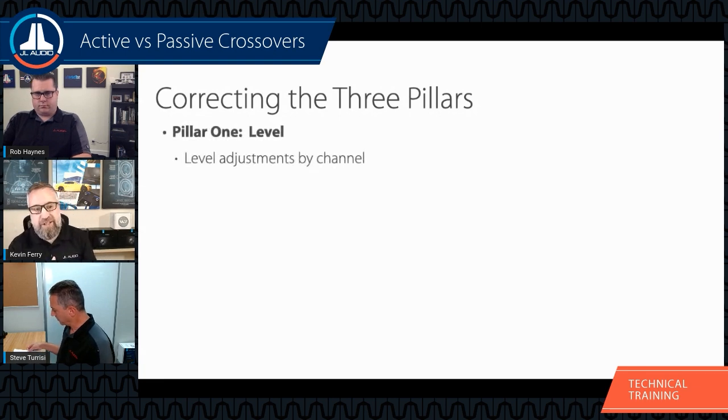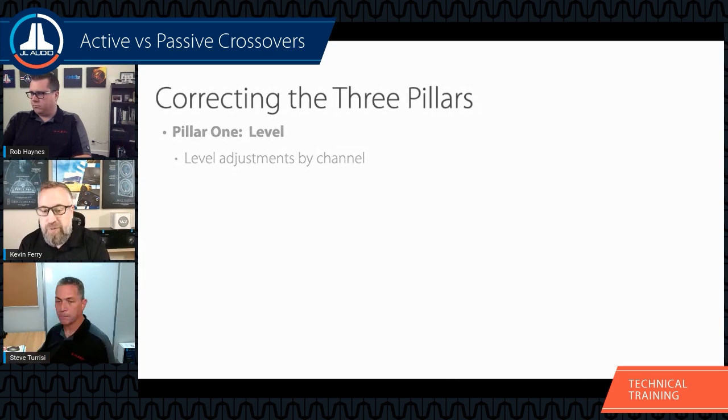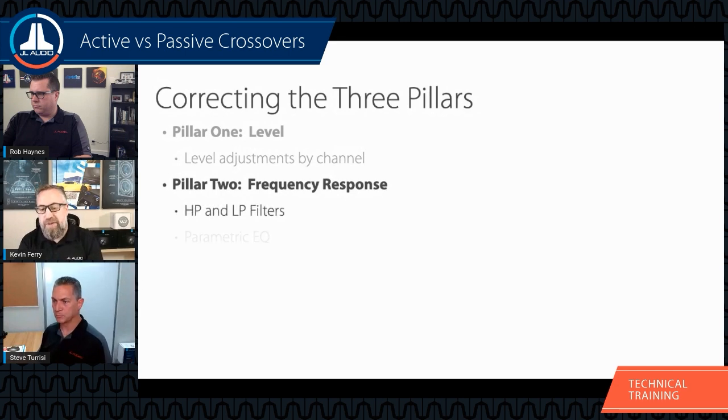You can get them fairly close, but it is going to take quite some time to go through and do that. Now, pillar 2, when we're using an active setup, again, we have the ability to adjust our high-pass filters and our low-pass filters separately to make those speakers really work well with one another in that given environment. And like we said, a mid-bass driver and a well-deadened door is going to react a lot differently